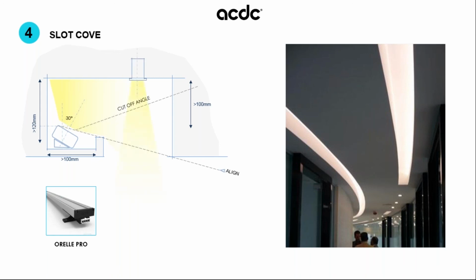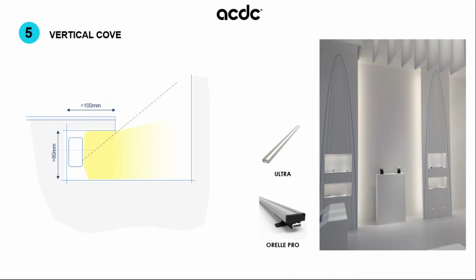What some people also do within the slot is incorporate downlights. That way you're keeping your ceiling clean of downlights, and you're incorporating that point source up and into the slot, so that the display, the accent lighting, is on whatever is on display below. So here you've got your cove and your downlights incorporated into one central zone. You're getting that ceiling feature with the cove, and you're getting that display lighting with the downlights.